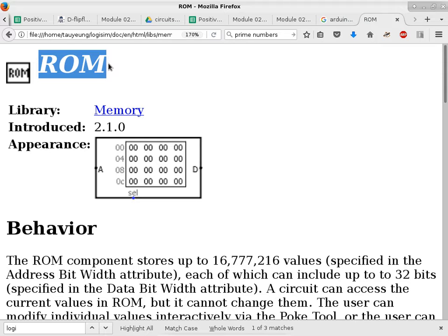So that turns out to be better than ROM, okay? Because now you have the capability of correcting a mistake in a firmware. Send out the PROMs to your customer and just say, okay, pull out that chip and put in the new version, and it's going to be okay. But it's kind of wasteful because the PROM that they pull out of the circuit board is no longer useful. You just throw it away.